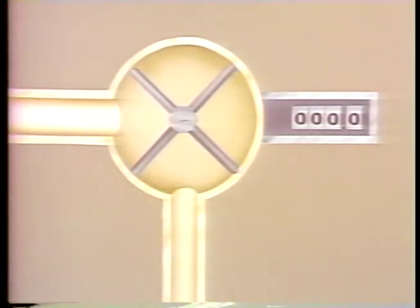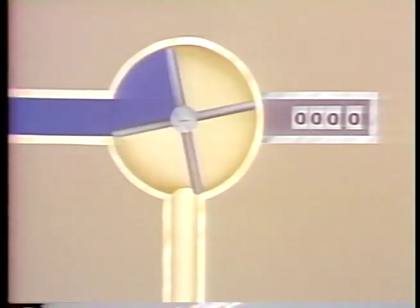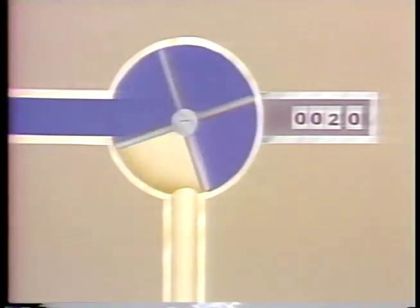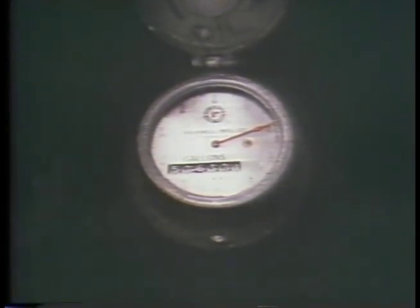When this instrument is installed in the flow path of a fluid, the fluid fills up each section of the paddle wheel, causing the wheel to rotate. The meter counts the number of times that the wheel rotates. Since each turn of the paddle wheel represents a known volume of fluid, counting the number of times that the wheel rotates over a given period of time will give you the flow rate. Positive displacement flow meters can be found in a variety of locations in a plant.